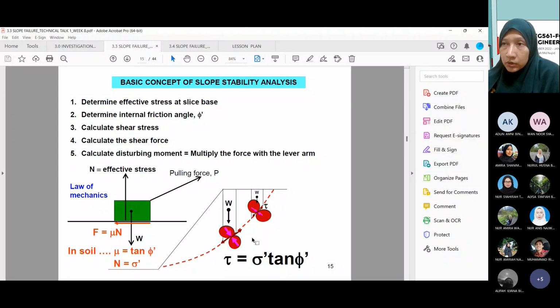So on this part, for mitigations, by using the numerical software, we can have a post analysis or a back analysis. With the back analysis, we can determine what the strength was during the failure, and then what is the best soil strength to prevent future failure. So these are the reasons when you are dealing with forensic engineering.